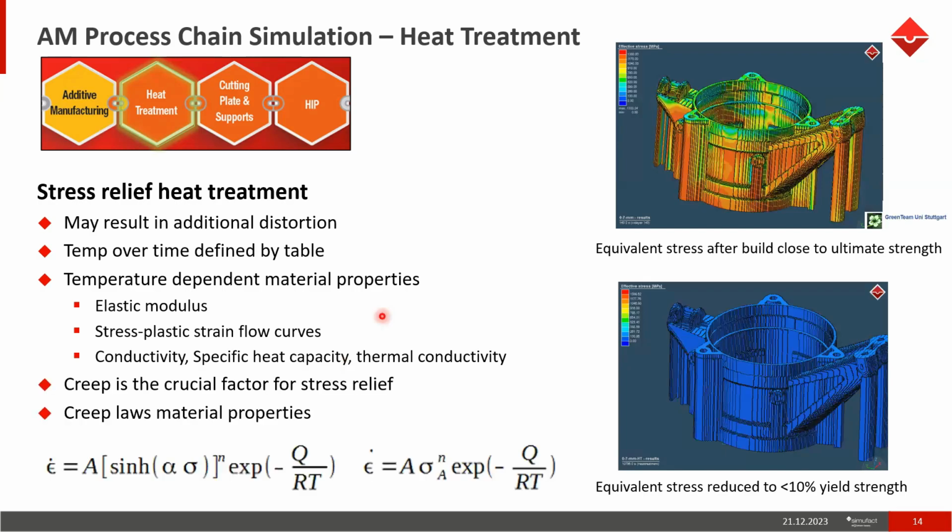And so for the heat treatment, we may require some creep properties. So there are some creep laws in the material properties, where we are using these kind of equations to calculate the residual stresses, the stress relief, for relieving the stresses. These kind of creep laws or material properties will be required to capture these kind of effects. Okay. So this is inbuilt in the software. What equations they will use, it is shown here.